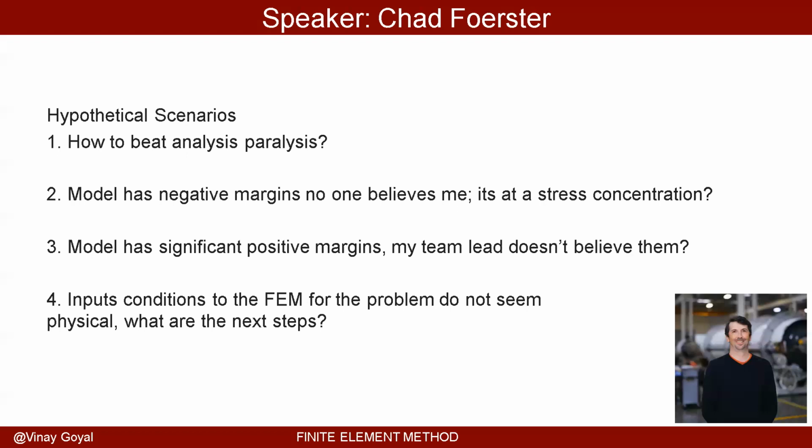So if it's some complex gear housing on an actuator, and you're like, oh my gosh, I don't even think it's worthwhile doing a shell element, then you take a step back and try to bound it another place. Maybe it's a solid element mesh, but with defeatured areas so that you only have a couple of elements through the thickness, not 20, but maybe 3, right?